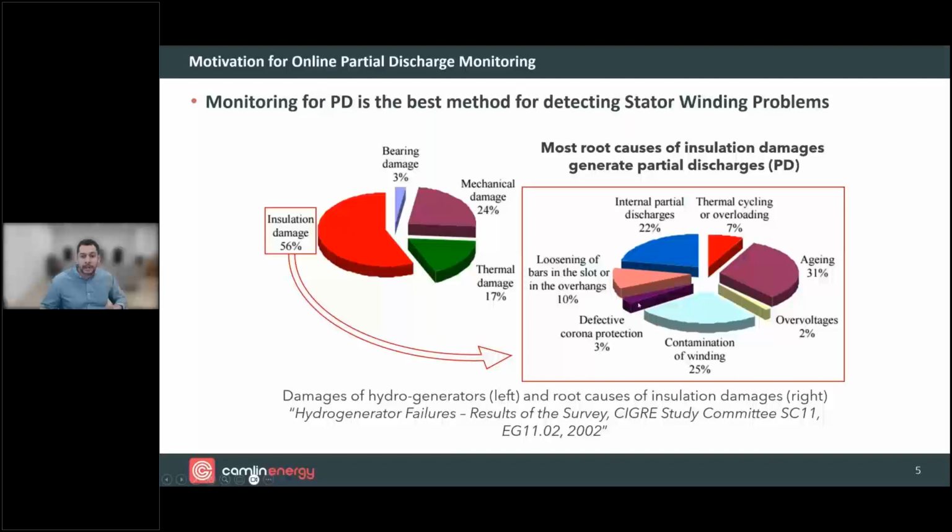But we know that each of these defects can ultimately lead to failures due to insulation damage, and each of them would be detected. There's early warnings that can be indicated by the majority of these by detecting online partial discharges. Okay, so we know that it's very important as a condition assessment tool to affect condition-based maintenance on the basis of detecting any of these potential defects if practicable, if we can actually affect a change, whether it's a rewind or some cleaning of end arm regions. We want to choose an effective maintenance to address any of these defect types if we can detect them early.